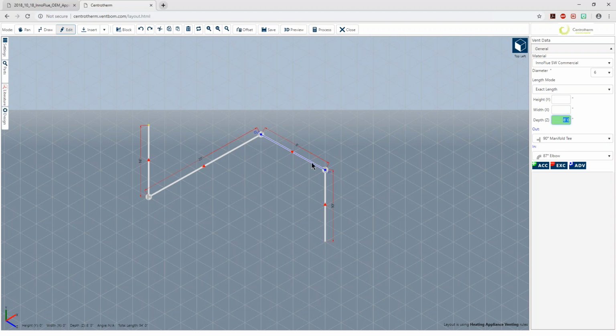So this is the same shared in, and it's an 87, so that's correct. Now you can see that the system has interpreted that it wants to put a 90-degree manifold T on there, which would be fine if the customer had requested some accessories like a drain or something like that at the end over here, but that's not how we're doing this one, so we have to change that. And all that's doing is offsetting horizontally, so we just need another standard elbow. So now elbow in, elbow out, and we're on to the next segment.